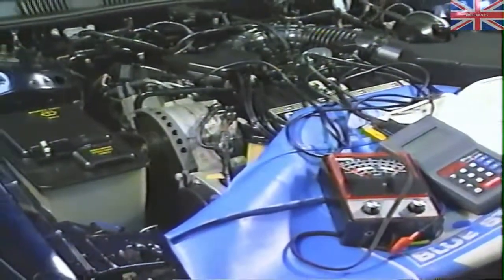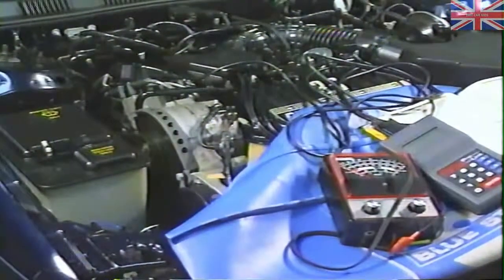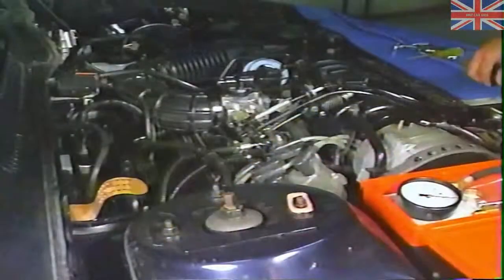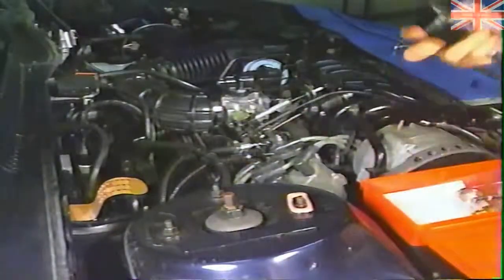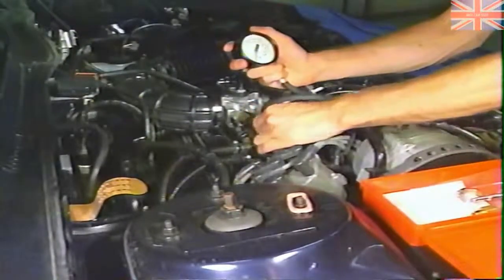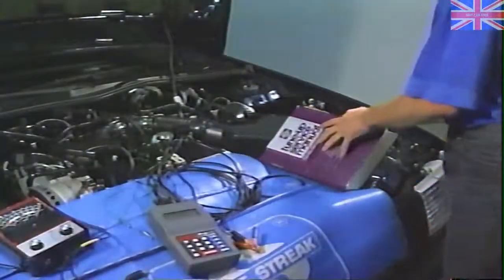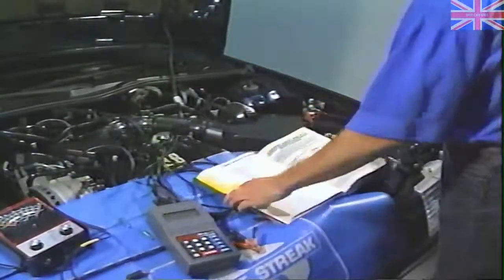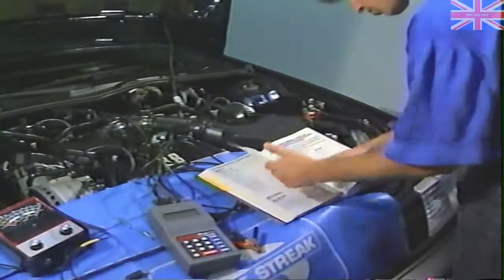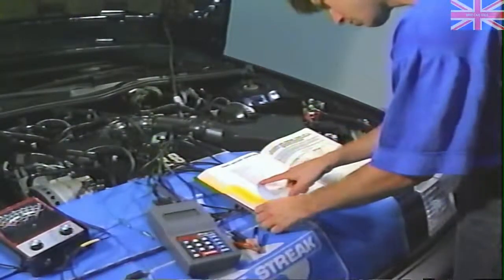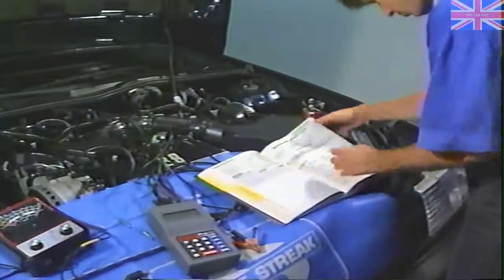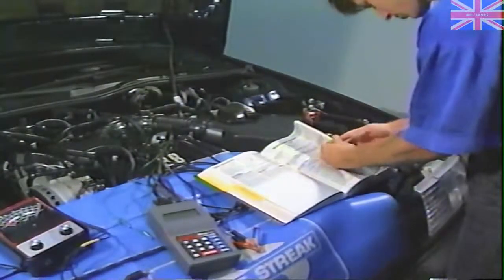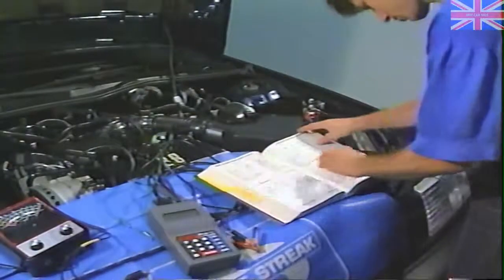indicator light. Since the complaint is intermittent, lack of power, or as the owner describes it, some type of a flat spot or a hesitation when he steps on the throttle, your first concern is to determine whether the problem is fuel-related or ignition-related. Any number of steps could be taken next. You could follow a symptomatic troubleshooting chart, or you could use the Ford H manual or any comparable service manual. But you should follow a logical sequence of testing.